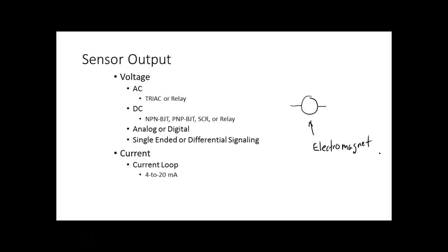And we looked at electromagnets next. And what advantage does an electromagnet have over a permanent magnet? We can turn it on. That's what a relay does. We can either turn the magnet on or we can turn the magnet off. We turn it on, it's going to attract something, right? You understand? So it's going to attract that armature or that plunger that we said. It's going to cause that plunger to move, right? And it's going to change the switches. So a relay is an electromagnetically controlled switch.